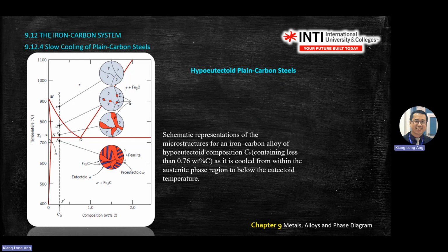You see, it grows on the line. Don't draw it inside the solid grain. Then the grain will grow. You squeeze out the gamma, then it drops, it becomes pearlite already. You will see all the blue color is the carbide, Fe3C, and this one becomes eutectoid alpha.